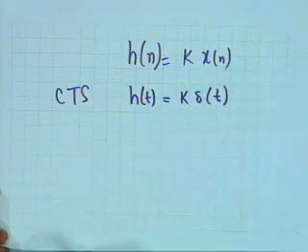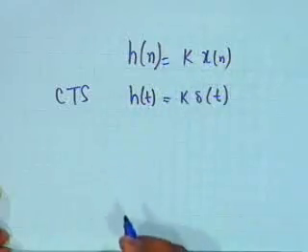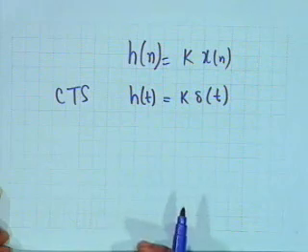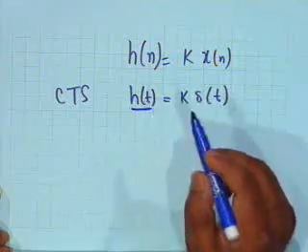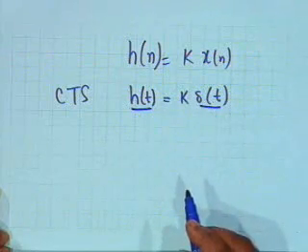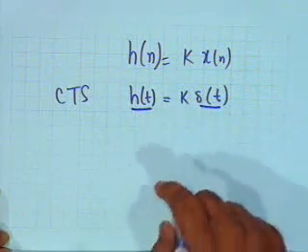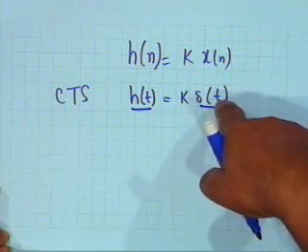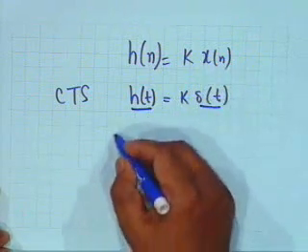Can you now say what is k? Is k equal to h of minus infinity to infinity? K is a determinable constant. If it is indeterminate, then you don't know what the system is. The indeterminacy of h of t is taken care of by delta t. Unlike the discrete time case, the amplitude of delta t is not finite. Can't you say what k is?